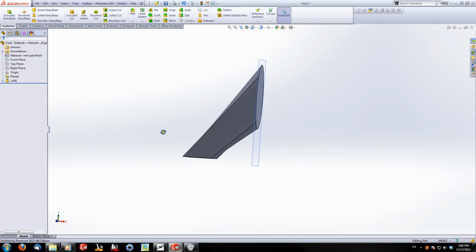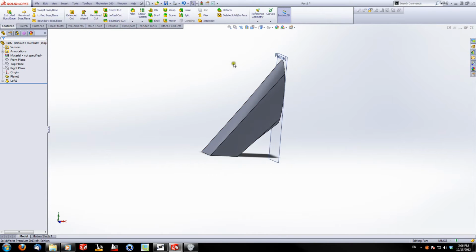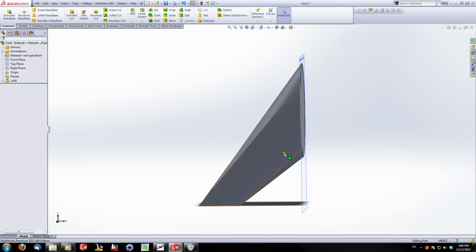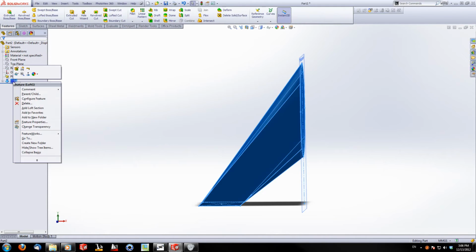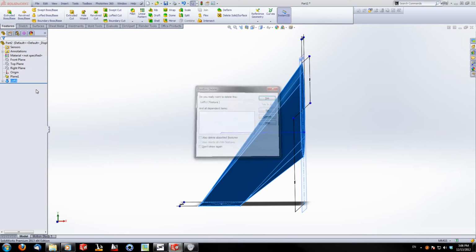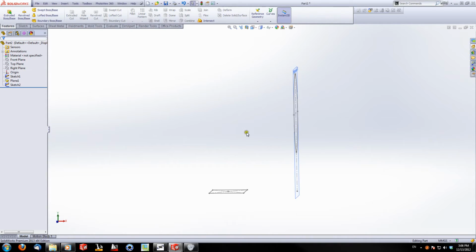So even though this may be okay now because I don't have any design parameters, it's just a doodle. Let's say I wanted to have a 90-degree bend or an elbow join the two together. Well, in that case, I'm going to undo my loft command by deleting it. If I want a 90-degree elbow connecting these two, I need to draw some guiding contours, if you will.